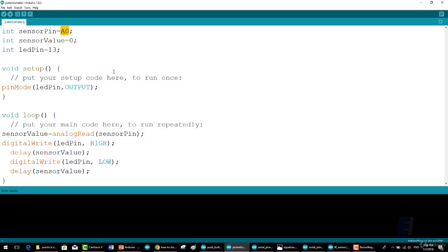If the system does not work, check the syntax and ensure the code uploads correctly. Next, check the connections to the potentiometer, ensuring that the middle lead goes to the correct pin, and the other pins are powered at 0 volt and 5 volt. If you bought a very cheap or old potentiometer, there is a chance it may be mechanically defective.